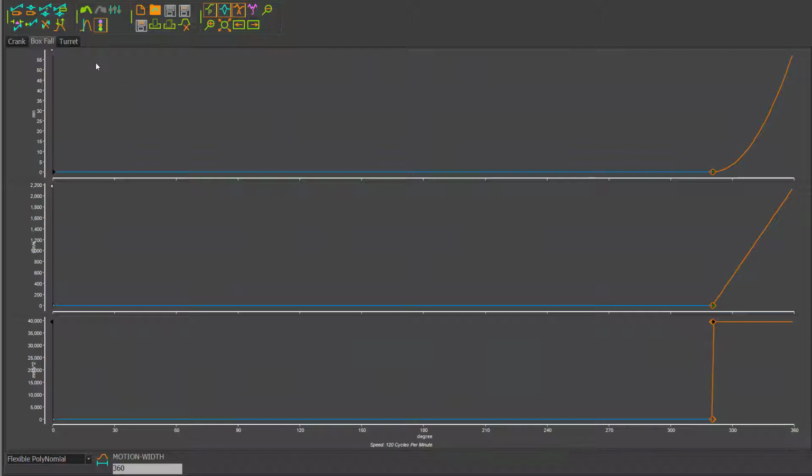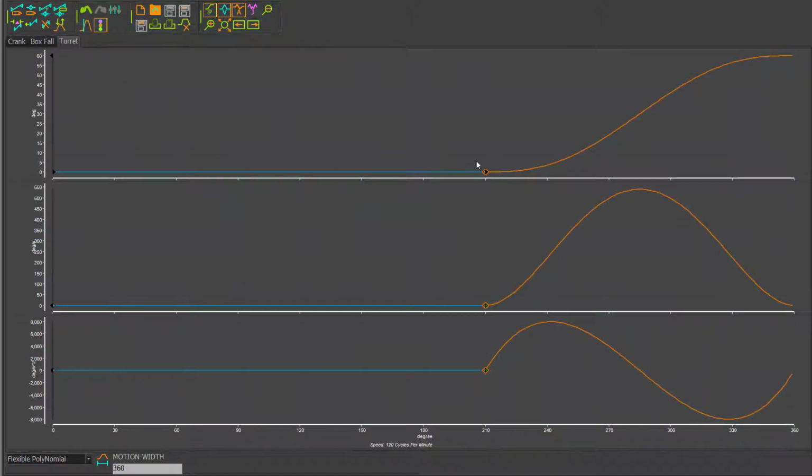position, as you'd expect. And then finally we have the turret motion, which is a simple indexing motion accompanied by a dwell. So the goal now is we want to try and get as smooth as possible motions, or motions which will have as small an effect on the forces and torques on the machine as possible. So we can start doing that now. I'm going to start by talking about jerk and what power controlling it gives us to improve motion design.